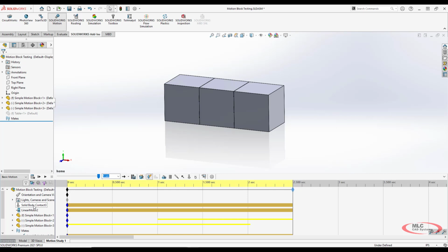There's a hierarchy to which one stops and which one else, and we'll talk about that a little bit later when we get into redundancies and things like that. But suffice to say, if it's not moving, odds are you have too many mates, everything's bundled up or bound up somehow, and you probably need to loosen things up to get it to where it can actually move.